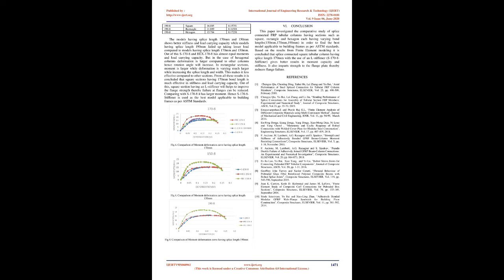V. Results and discussions. A. Static analysis. From the analysis, an equivalent plastic strain was observed in each model. Fig. 3 shows the equivalent plastic strain distribution in Hex 170-8 model. The plastic strain observed is mainly concentrated in the flange plate region of splice connection, thereby creating the plastic deformation in face of the connection plate.